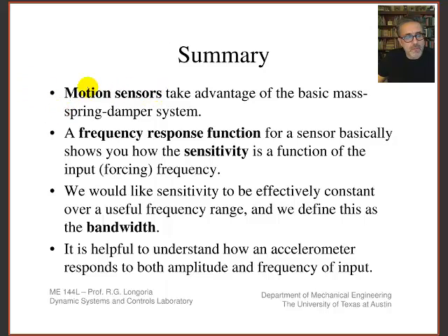And I'm done. So again, motion sensors of this type, displacement, acceleration, take advantage of basic mass spring damper configurations. A frequency response function is key. That's why this is a good lab actually to tie in when you're talking about transfer functions and frequency response functions, and I try to do that. The sensitivity is that function, and you should hopefully, if you had an opportunity to learn about frequency response in systems, you can see that the sensitivity is something that comes out of frequency response, and in that way it's related to the basic makeup of your device. It's related to the masses, the springs, and the dampers of these particular elements.